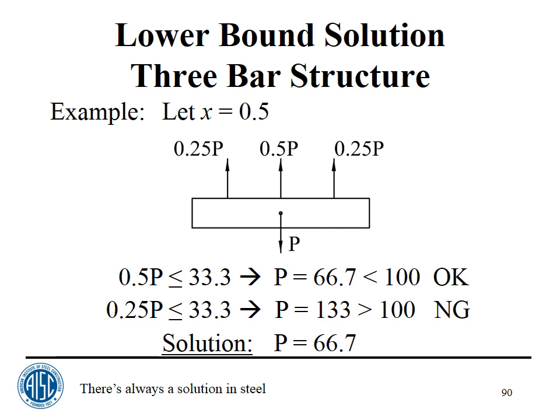In addition to that, you've got things like pin connections not really being pinned, and moment connections not really being totally rigid, et cetera, et cetera. All of those things tend to put error into your solution, and you come up with, I think, a satisfactory solution because of the lower bound theorem, but you're not going to get the force distribution that you think you have.